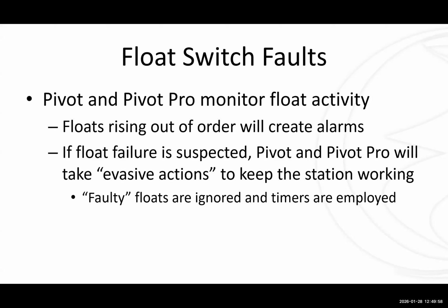because it says, okay, maybe a float has gotten stuck. Or let's say that your stop float at the very bottom doesn't come up, but the start float above it does. That's not a condition that should happen. If the middle float comes up, the bottom float should be up too. So if it sees an issue like that, it sounds an alarm. But beyond just sounding an alarm, it takes what we call evasive maneuvers, an evasive action. It tries to make sure that pump is going to run and keep that pit pumped down.